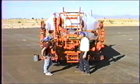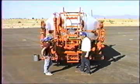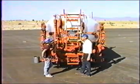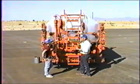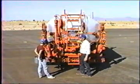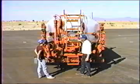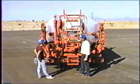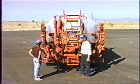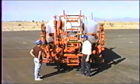If it's frozen up beyond that, then the only choice you have out on the job is to heat up the spray bar. On a truck like this that has diesel heat, your only choice is to get a rag and put it on a piece of fence wire and tie a knot in it and soak it in diesel and light it and burn it, and you warm up a piece at a time, and it's a long, slow process. If you happen to have a weed burner, you can do it a little bit quicker, but you can see you have to be extremely careful. You can see all the hoses, all of the fittings, all kinds of things that would burn up easily with a weed burner.